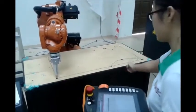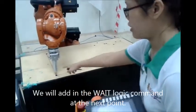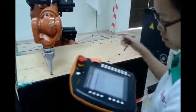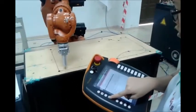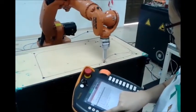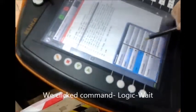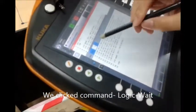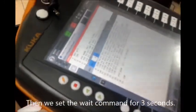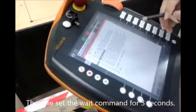So we would like to add the wait logic command after this point. So when the KUKA robot moves from this point to this point, we would like to add wait. Okay, now we would like to click command, logic and wait. So we just set it 3 seconds, so it will wait for 3 seconds. Okay, command okay.